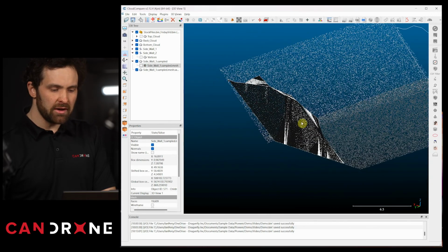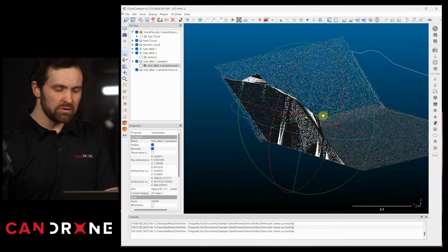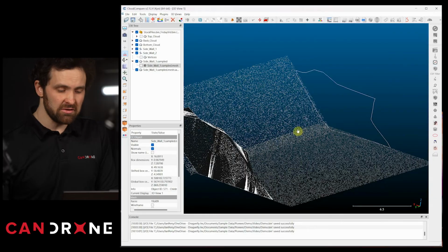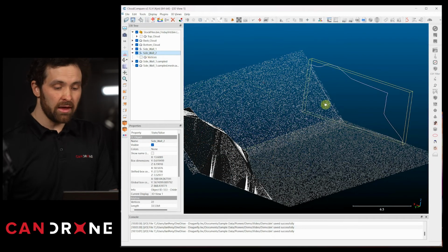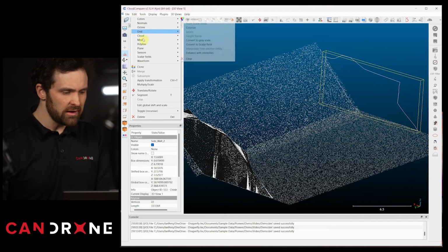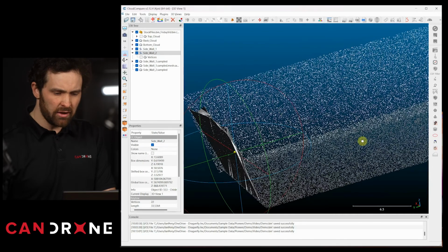And you can see we've created a point cloud and the sidewall we need in order to finish this enclosure for our volumetric analysis. We just go over and do that one more time at the other sidewall. So I highlight that, I go into Edit, and I go into Polyline, sample those points. 1,000 is fine.